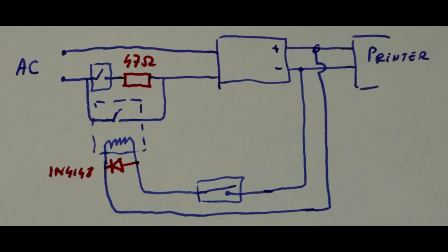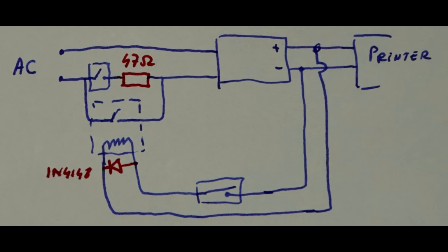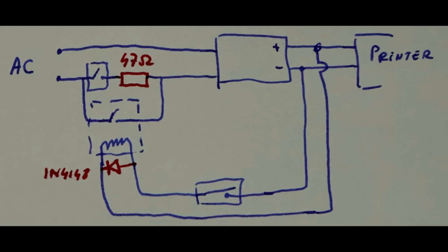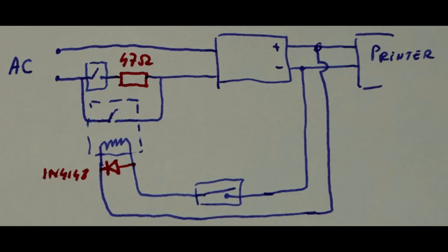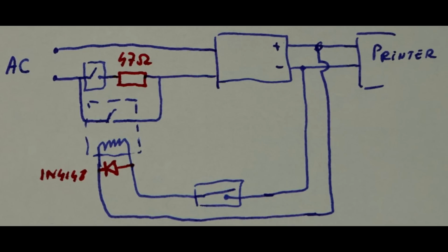So finally, coming back to the practical circuit I was talking about last time, the one with the broken switches, how did I end up fixing it? Well, for the voltage spike, I used a basic diode. The normal operation current of the relay is below 200 milliamps, so I went with a 1N4148, and I could have used a lower current rated diode, but I just didn't have one.